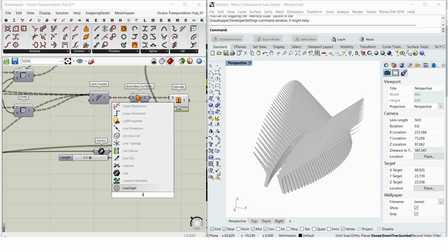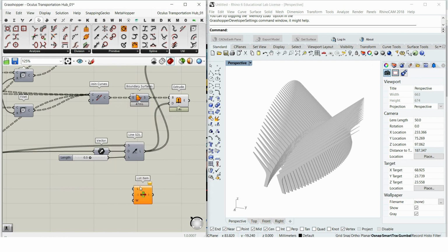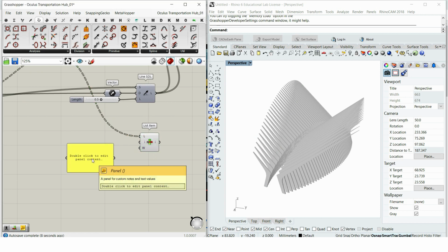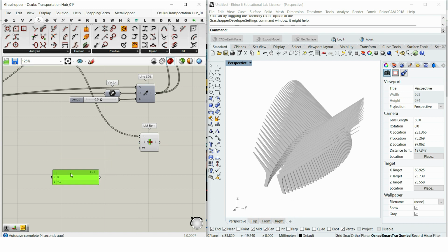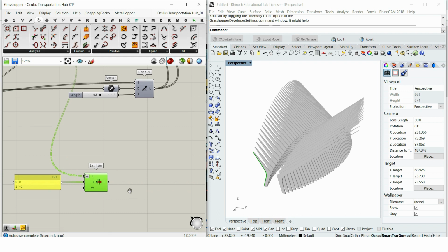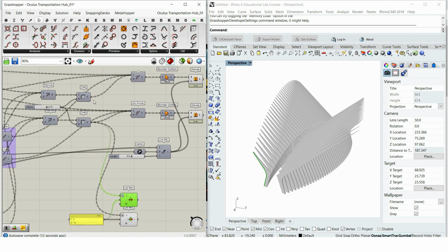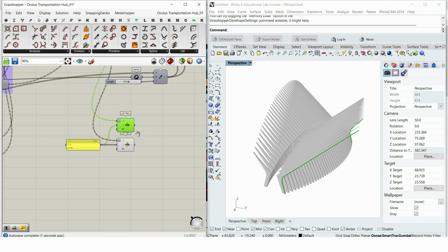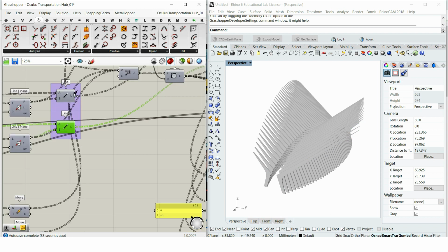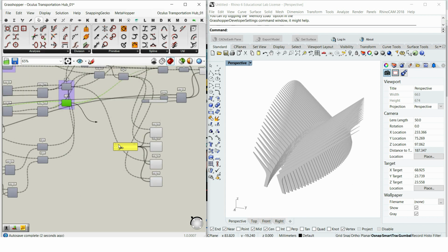We are going to start from creating entrances elements. First, we need to select several curves from the start and the end by using list item component. Make a panel and choose multiple data, then put 0, which will always take the first element of the list, and -1, which will always take the last. And don't forget to flatten the list and apply the same copy to all the curves you need. For example, the upper rays.